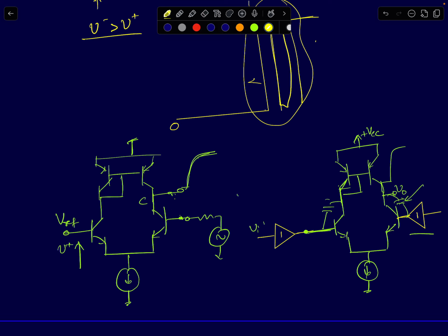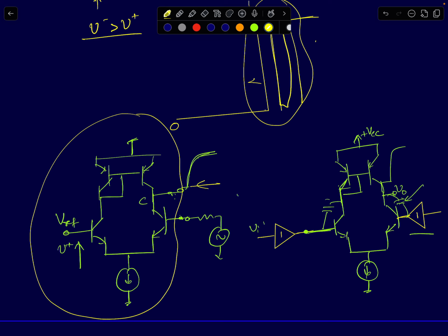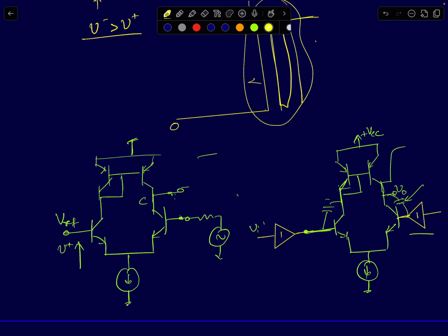I just assume there is an input capacitance, and there is a coupling capacitance between the output node and the input node. Where does this coupling capacitor arise? So here I've shown the simplest realization of a comparator using a common emitter, differential input to single-ended output amplifier. Here the input is applied to the negative input, so this is your inverting terminal. This is your non-inverting terminal where we have applied Vref. And your input signal is slowly decreasing. It has gone lower than Vref. So this output will suddenly go high from 0 to VDD or whatever, from a lower voltage to a higher voltage.